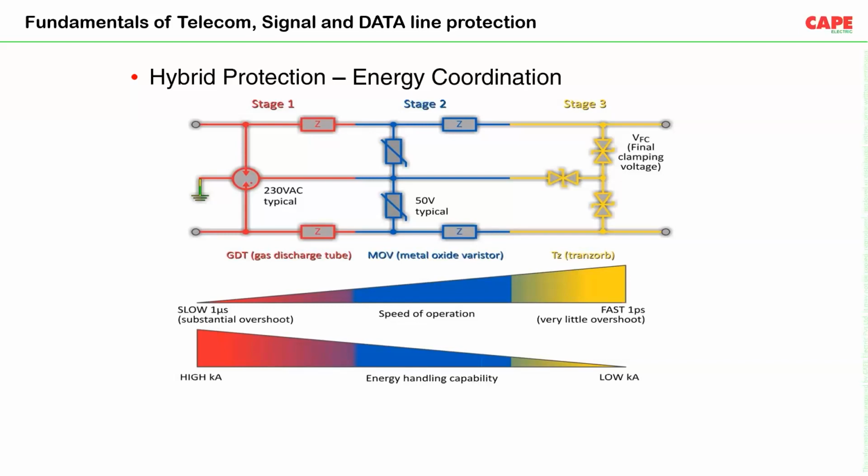So now our SPD, our GDT, for which the clamping voltage was 1400 volt, now operates. Now these values, I've just assumed the values. They will change again from case to case. It is going to change, and for the same reason, the value of this impedance becomes very important.